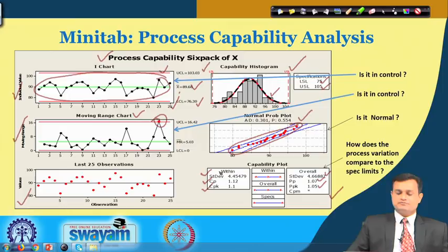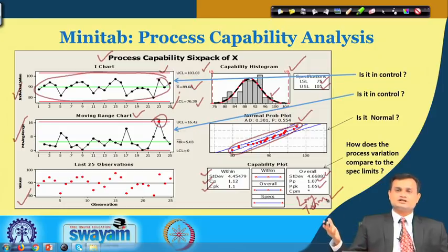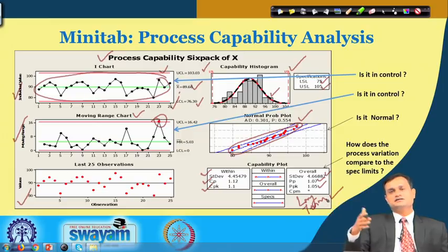So, it is capable. When I look at the long term, Ppk and Pp values are also greater than 1. I would not say it is a six sigma process, because for that I need to be close to 2, but technically, greater than 1 means my processes are capable in terms of performance, that is the spread and variability in terms of potential, and Ppk in terms of location or shifting of the center value.